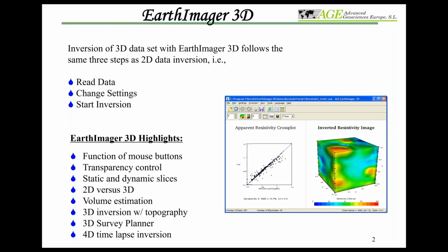It will help you adjust the forward model parameters, data removal parameters, and inversion parameters easily. In this case, you can do it quickly and easily. It works for most of the data sets. If you have anything special, of course, you can go through settings and change all these parameters, like data removal parameters, mesh parameters, forward modeling parameters, and so on.